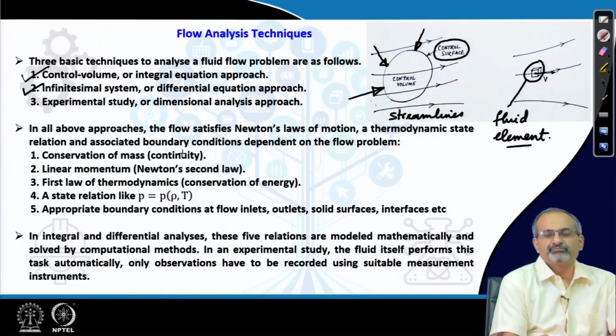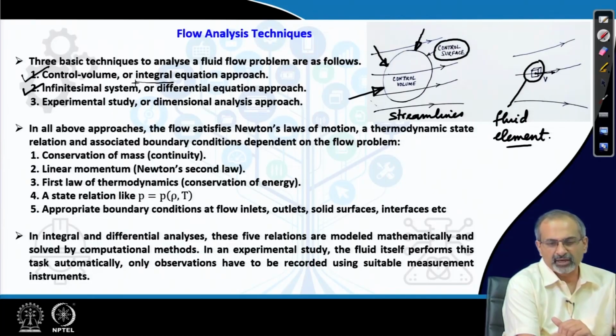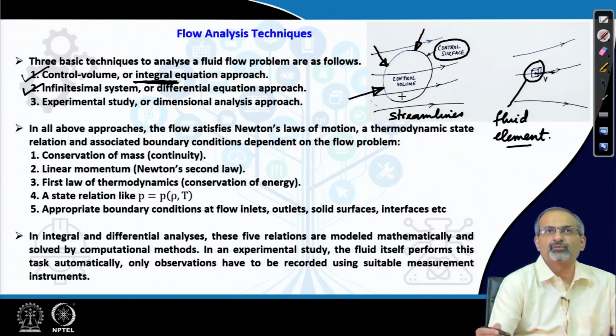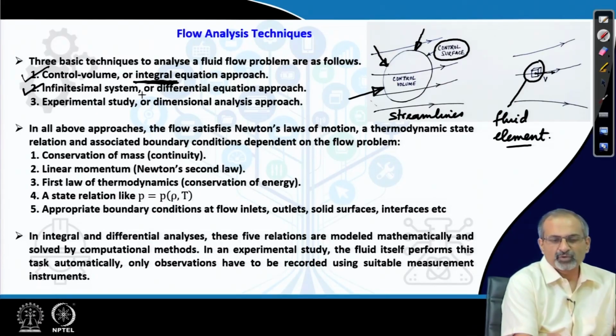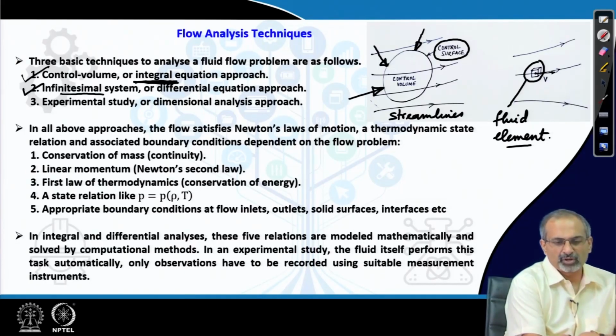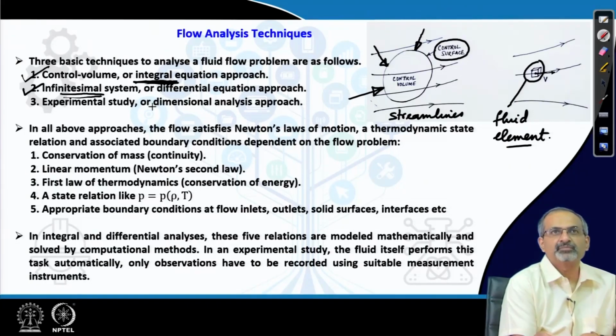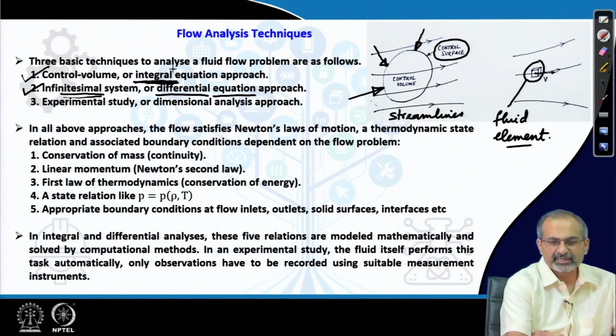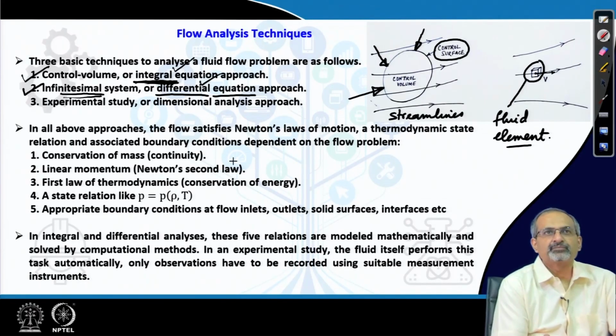So, control volume is an integral approach. We have a large volume and we are essentially measuring the flow parameters as it enters, moves through the control volume and leaves it, while as far as the fluid element is concerned, it is a very small volume. So, it is an infinitesimal system, and we would take a differential equation approach when we look at such a small system. So, it is an integral approach here, while a differential equation based approach here.